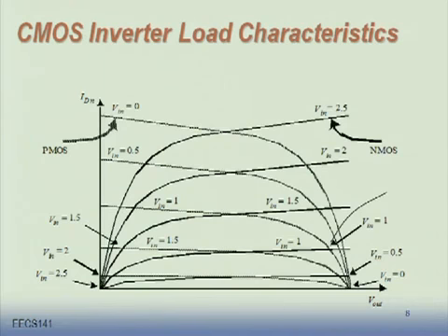When the transistor turns on, say, at 0.5 volts, that is like 50 millivolts more than the threshold, the NMOS curve is this low one and intersects with the PMOS curve that corresponds to V in of 0.5 volts, which corresponds to the VGS of 2 volts. So there is some intersection here. Next one is V in of 1 volt, corresponding to the PMOS curve for V in of 1 volt, moves up there, moves like that, moves like that.